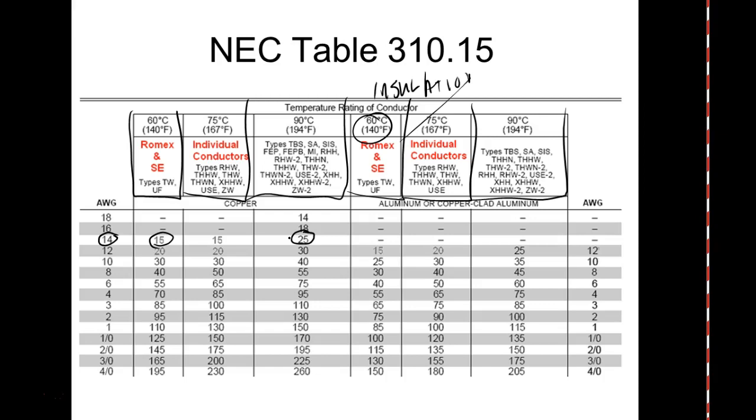It's called a derating factor, and they give you a multiple. Here it would be a fraction, like 0.9, and you would take it and multiply it by 0.9, and that would be the amount of ampacity. So what that means is I might say, okay, it's rated at 15 amps, but when I start derating the thing, all of a sudden I say, well, I can't use 14, I need to go to 12. And then we derate that, and as long as it's more than what we need to carry, then it's okay. That makes sense? Everybody okay?